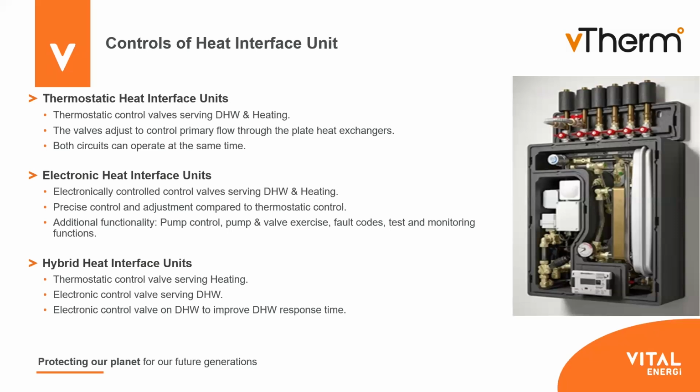And then we have hybrid HIUs, which are being phased out, where I've mentioned that we would have had some form of thermostatic control on the heating. We would have an electronic control valve on the domestic hot water, and that is to help improve the domestic hot water response time that's required to meet BESA testing requirements.